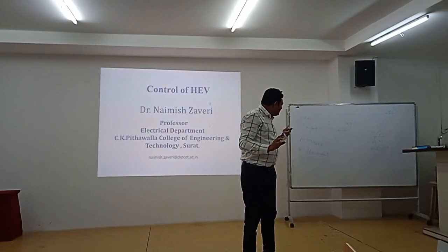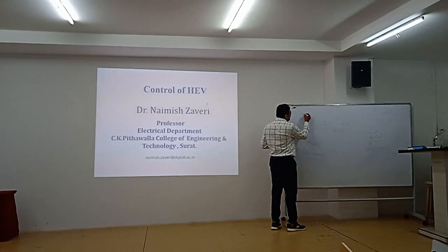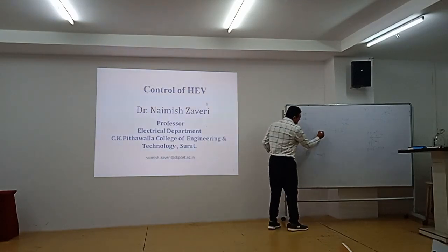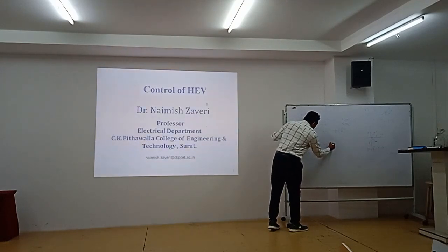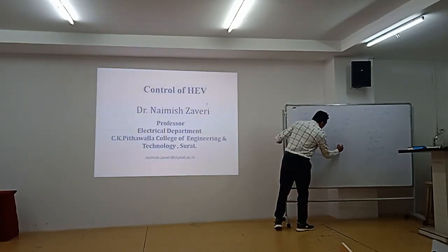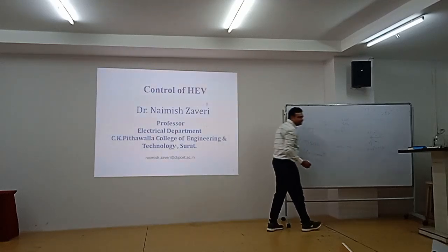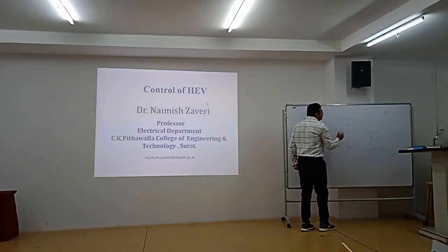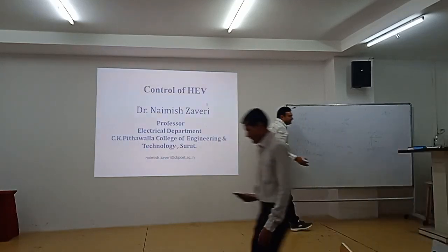It is dependent on power angle, and so suppose here there is a 1 at an angle of 2 degree and there is a 1 at an angle of 1.5 degree. This reactance is 1, right? So the power is equal to 1 into 1 divided by 1, sine of 2 minus 1.5 degree. So one time it is positive, and the moment this angle changes, instead of 1.5 it becomes 2.5 degree, right? So this power becomes negative. So it's a huge reversal.